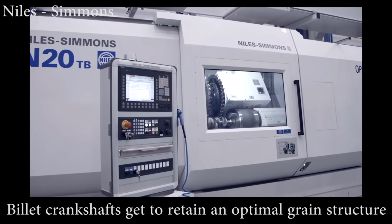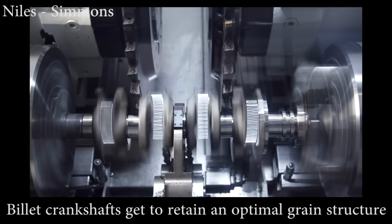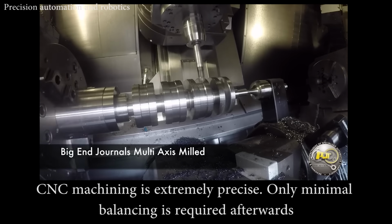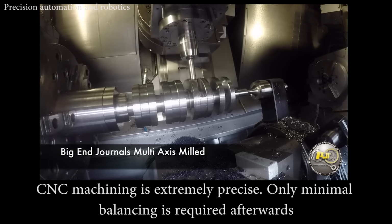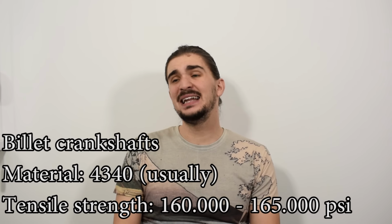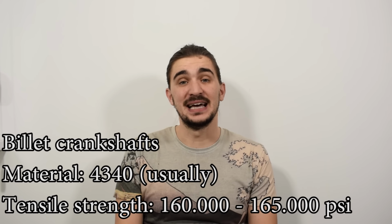Now, both forged and billet crankshafts get machined, but the machining is actually seen as less disruptive in the case of the billet crankshafts, and they get to retain an optimal grain structure. Another benefit of CNC machining is that it's very precise, and it enables very precise shaping and location of the crank throws. Now, this enables higher strength and easier balancing later on in the process. Typically, billet crankshafts are made from the 4340 alloy or better, and they usually have a tensile strength rating of around 160,000 to 165,000 psi.